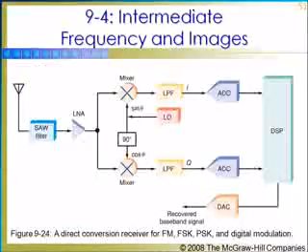We have here another figure. This shows a direct conversion receiver that is typical of those that use digital modulation. So first, the incoming signal from the antenna is sent to a SAW filter. So this SAW filter provides some initial selectivity. While next is the LNA that provides the amplification. The output of this LNA is fed to two mixers.